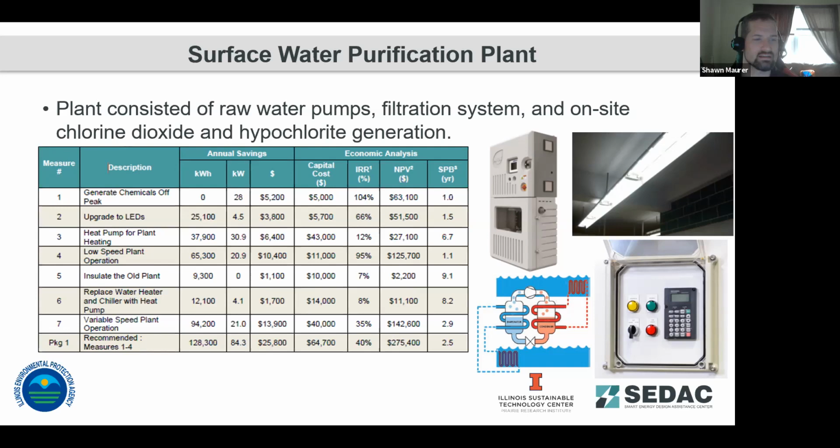They had existing HVAC systems that were electric heating and 13 SEER AC units, looking at high efficiency units for those. And then we had an option for swapping out those dual speed pumps with variable speed pumps instead that had a longer payback period. So we went with the shorter payback period for that.